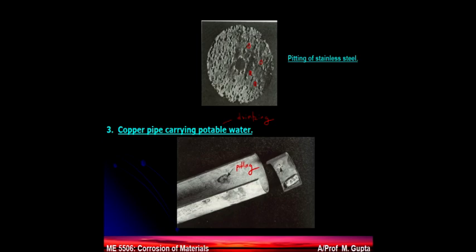Now what happens is, if you are transporting some liquid at no pressure, normally you have to apply pressure to transport, but if you are transporting in a way that no pressure is required, then maybe the pipe will not burst. But if pressure is involved in the transmission, then these holes may become a site of stress concentration and you can have a pipe burst.